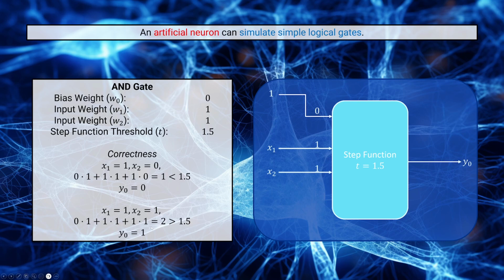So this is simpler, if you ask me, than the NOT gate in terms of design or understanding it. We just let the inputs come in as normal, 1s or 0s, and then we just count. We use the threshold to count them. If there's at least 1.5 of them, that means there's 2, given that these are binary valued. And we know that the AND should be output as a 1 now, and otherwise we will output a 0.